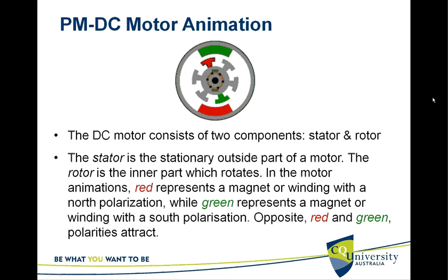Now this is the animation. There is a bit of text. I'll just go through the text also, but if you just look here, this is a PMDC motor obviously. So you got the permanent magnets here producing the air gap flux, and then these are the brushes. So as you could see, through the commutator segments you supply different windings, different poles of the armature in different occasions.